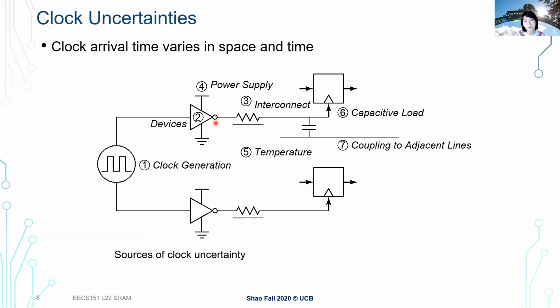So one thing you really need to consider is that when you have a large piece of hardware where you need to send your clock to all the registers, you have plenty of registers in your design, all of them placed at different places and also routed differently. So all of them could potentially have a different delay. And that's already one component of the non-ideality that is triggered when we have different delays.